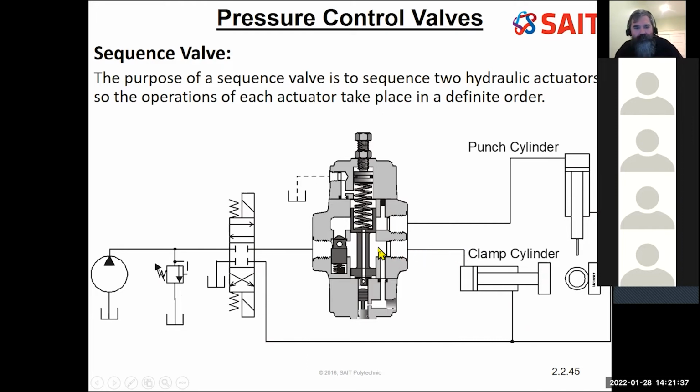Oh, this is a bad drawing. Yep. Back to tank. Yes, there, that way. I misread that. Fluid coming in, pushing the cylinder back, fluid coming through this main pressure line. The check valve is open, and it's also got this hole through it, allowing fluid to go back through to the reservoir. Sorry, messed up that one.